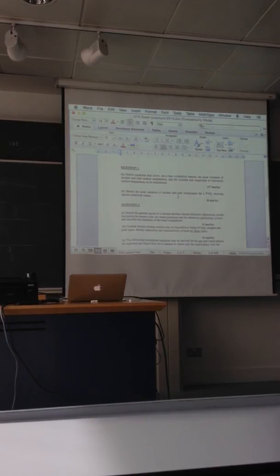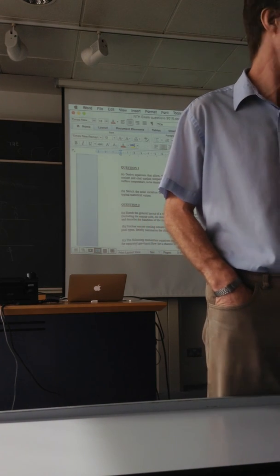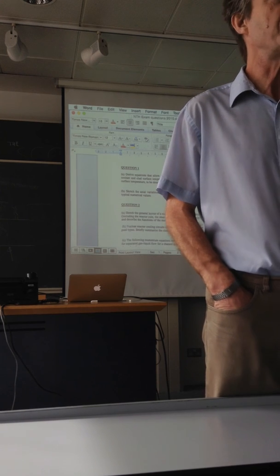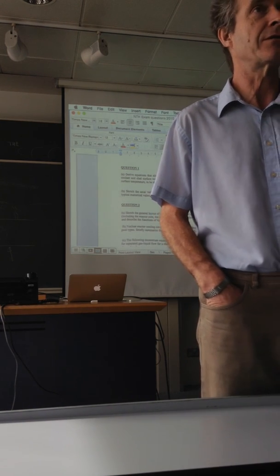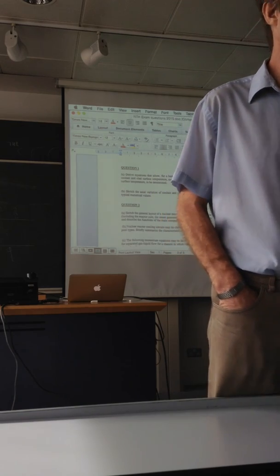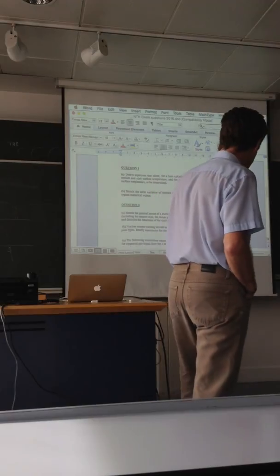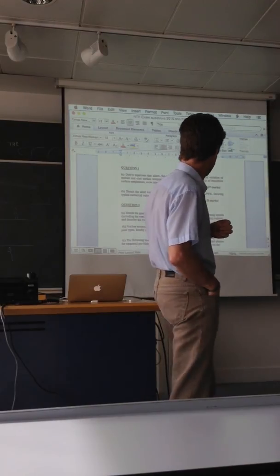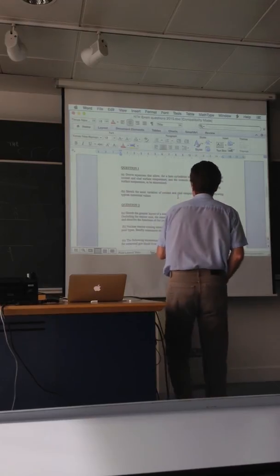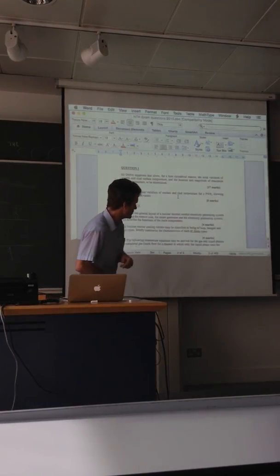So, okay, the bare cylindrical reactor, that's the bit that's telling you, because these people have also done reactor physics, for you to know that for a bare cylindrical reactor the axial variation is cosinusoidal. So that's why that's in there. We're not telling you it's cosine axially, but you need to use your knowledge of reactor engineering to get that. Axial variation of coolant and clad.